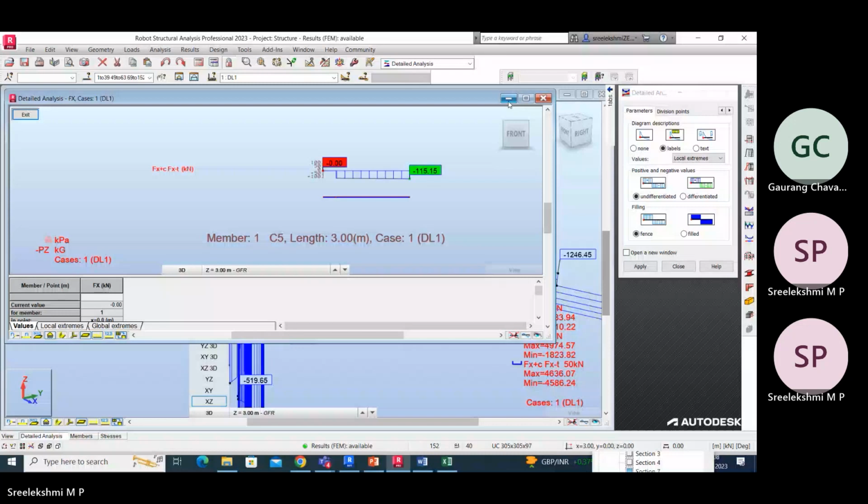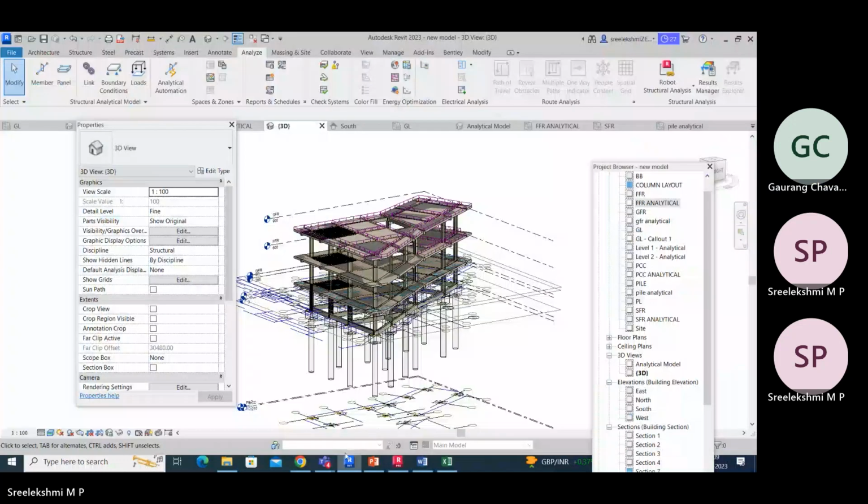Similarly, we can't open all files in other software. There is a format called IFC, which means Industry Foundation Classes. If we are exchanging data in that particular format, we can open it in most BIM software. For example, in File we have an Export option, where IFC is available. So we can export to IFC and then open it in suitable BIM software.